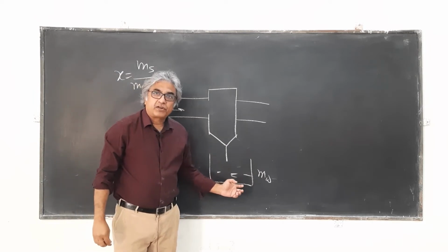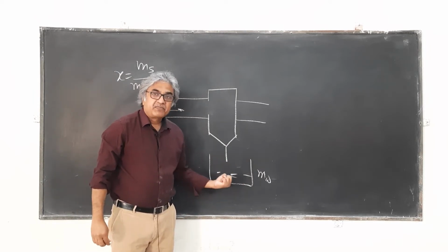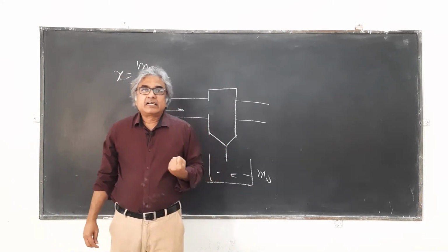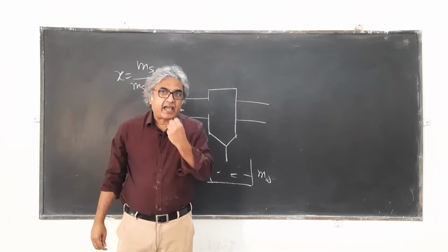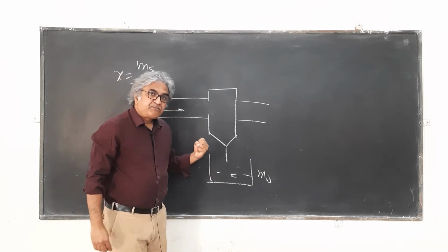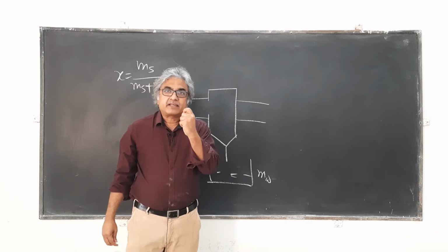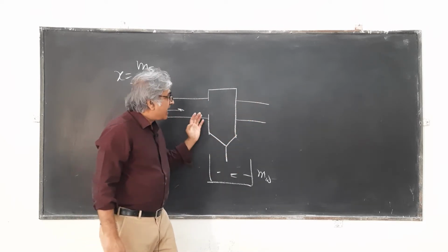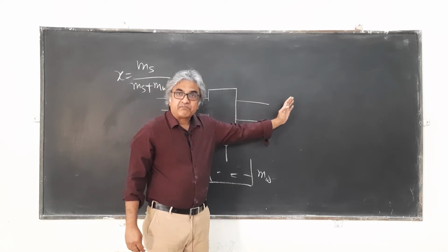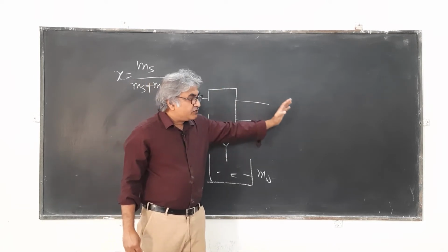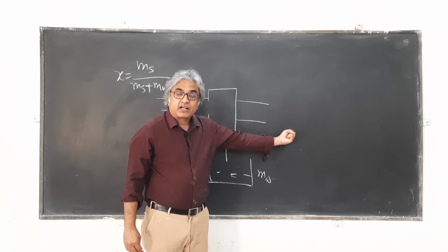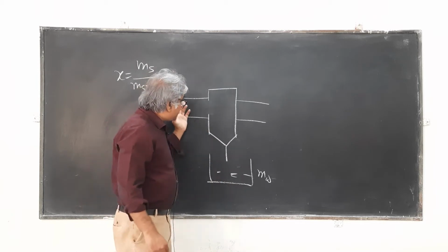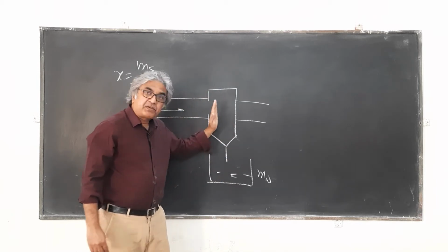Mw is the mass of water which you have collected here. Now this is a very crude kind of thing, and the result won't be accurate. One can imagine why. There could be some fine water particles that bypass this obstacle, they won't be collected here, and they would flow with the steam. So you condense that steam and consider that as the mass of dry steam, which could be an overestimation. It might contain certain water particles which you couldn't stop here.